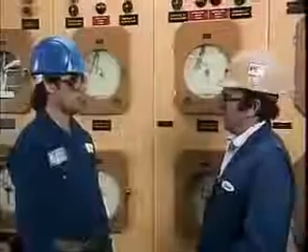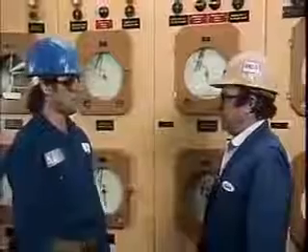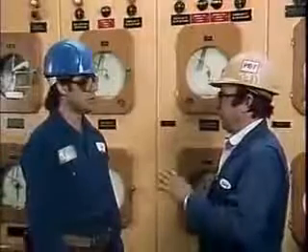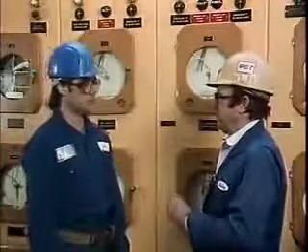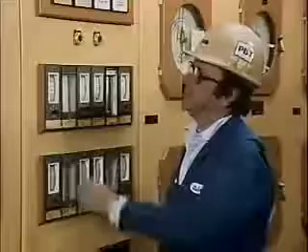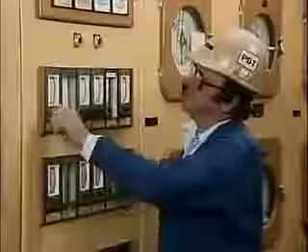In our example, the compressor is used to compress a gas that is supplied from storage tanks. Many compressor startups are performed by more than one operator, so good communications are essential. Before the compressor can be started, operators must verify that the compressor's gas supply is available and that the controls are set in the proper positions.